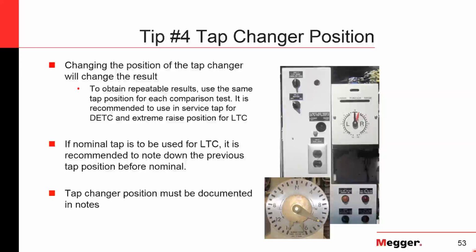Then as you move over into the mid-range frequencies, that's where your winding is. So now it's kind of odd because you'll see that there's an issue with the winding. You look at different results and see, okay, if we have a frequency shift, or a resonance point shift, or loss of resonance, it's indicating there's an issue with the winding.